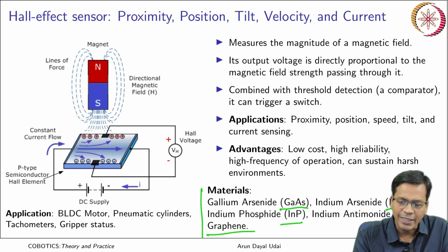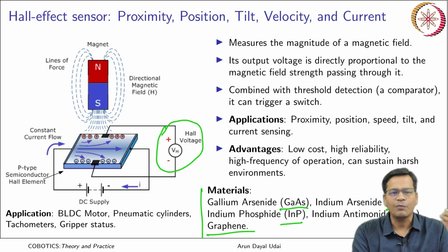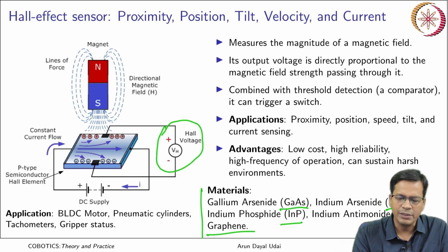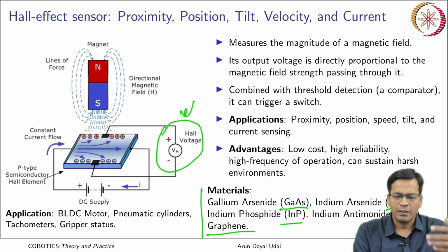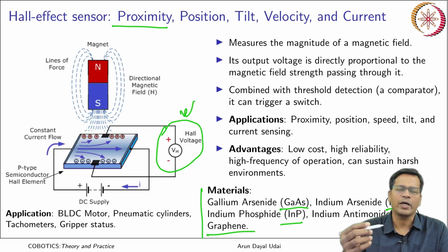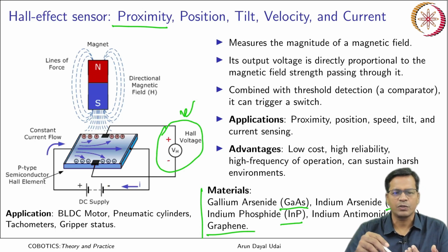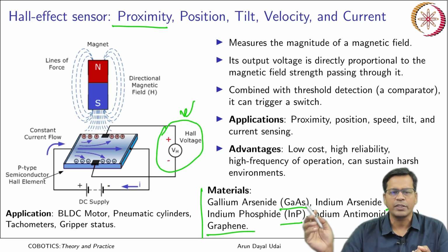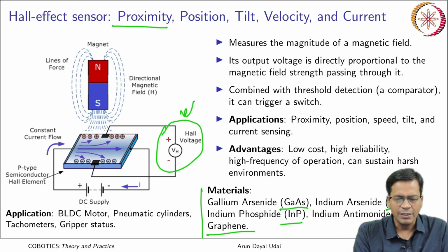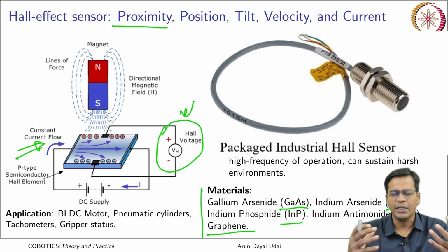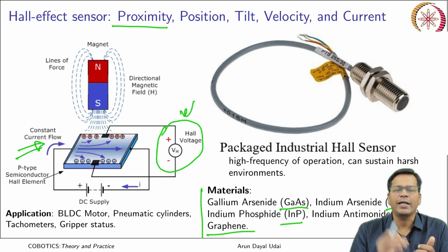Again, this is the sensing element, okay, it gives you a voltage signal. Now the complete sensor is a package which will process this voltage signal. If it is inside a proximity sensor, it will digitize it to 0 and 1. It can have a communicating circuit also which can transfer it using I2C, or it may be Profibus, Profinet. So that communication circuit is within also. So this is just a sensor, okay, a pure sensor. So it has to include many other components for processing and transmitting.